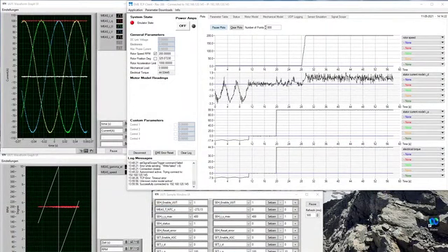This is a screenshot of the user interface on our host PC. On the right-hand side of the screen, you can see the user interface of the HIL system, where all parameters of the motor, inverters, as well as the scaling gains and other required parameters can be set. In the user interface of the HIL system, we not only set the HIL parameters, but also observe HIL internal values. Different test scenarios such as change of rotor speed, simulation of wrong measurements, and many other test features can be emulated.